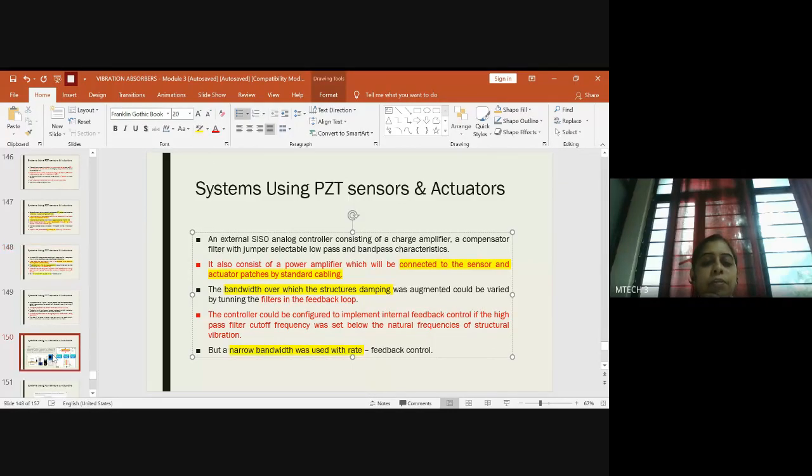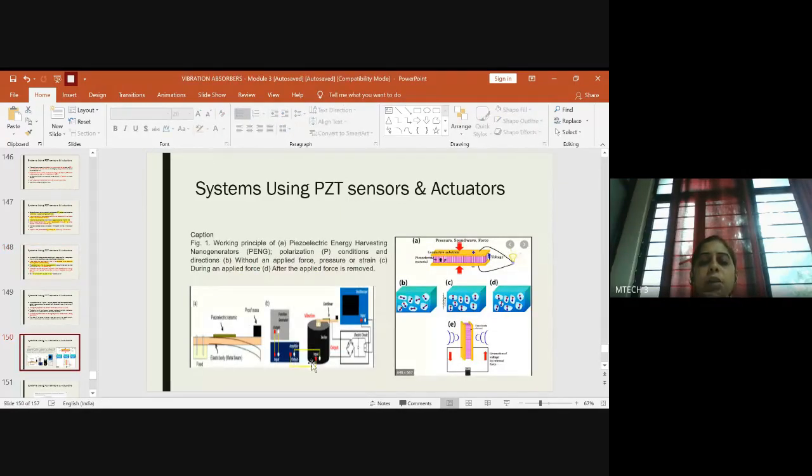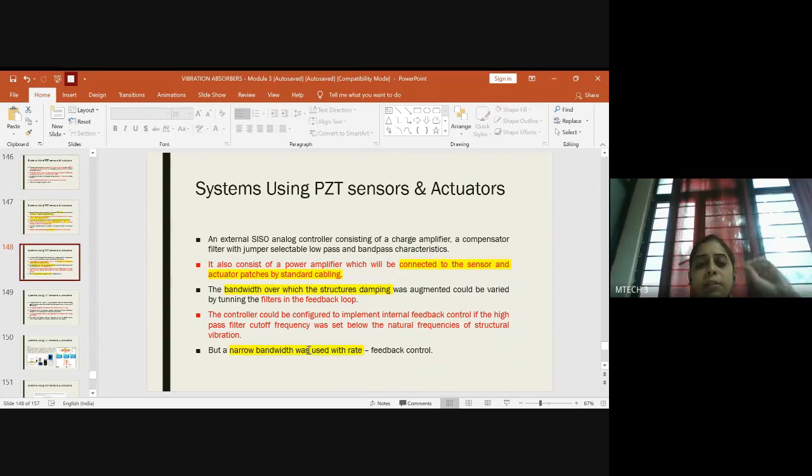So if you don't have a feedback loop over here, unnecessarily you'll be having high variations in the vibration, and you'll be adding more amount of dampers, that is to say the vibration absorbers, to control the strain rate. But if you have an automatic feedback controller here, you can directly reduce the vibrations and you can get the required strain rate data in the oscilloscope. So that is very much essential. This person also claimed the same thing.